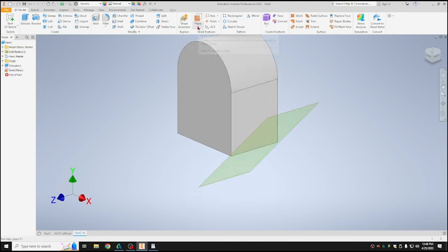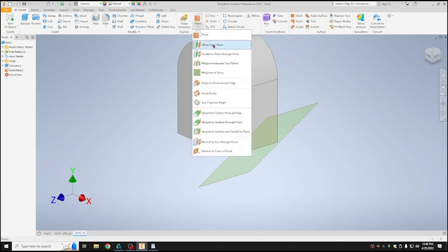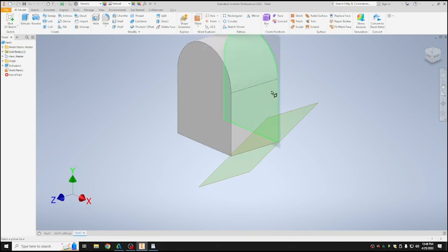Then you're going to offset a second plane. So go to plane, offset from plane, click on this plane again. And now we're going to offset it 4 millimeters away. Make sure we're going in the opposite direction, away from us, not that way. So if you're oriented this direction, make it a negative. Okay, so it should be back here. All right, 2 planes, looking good so far.